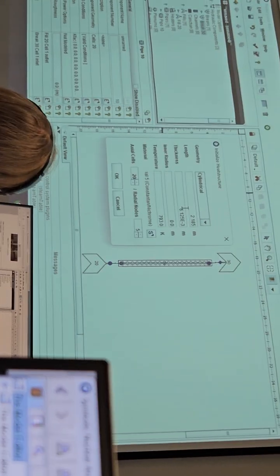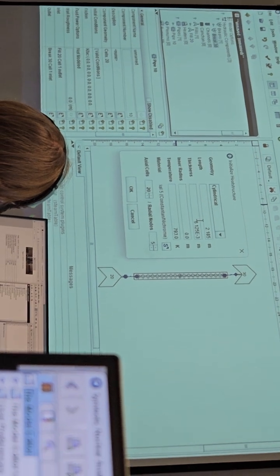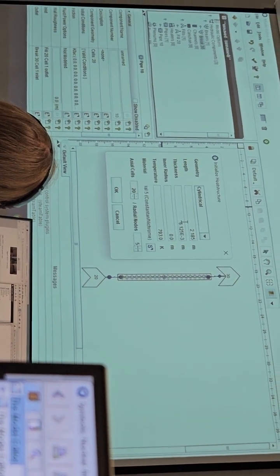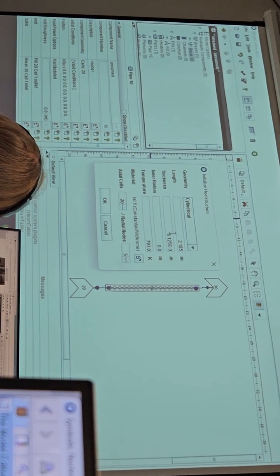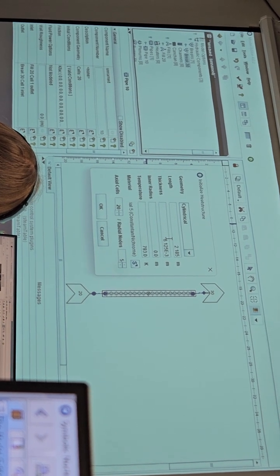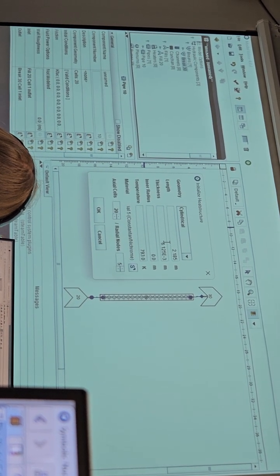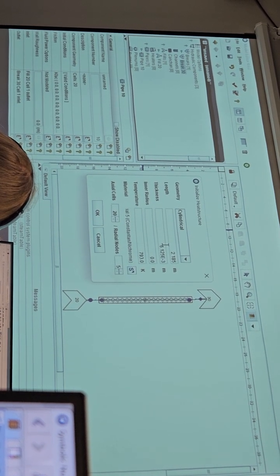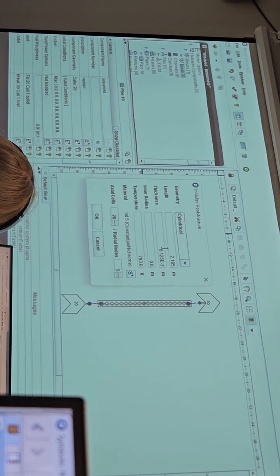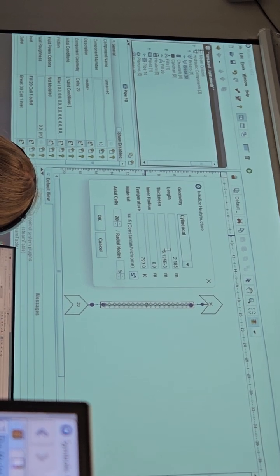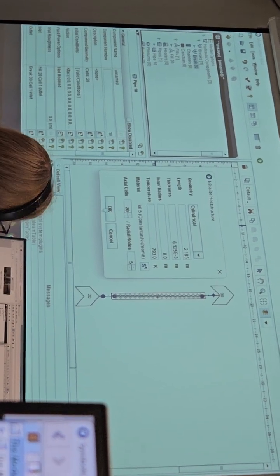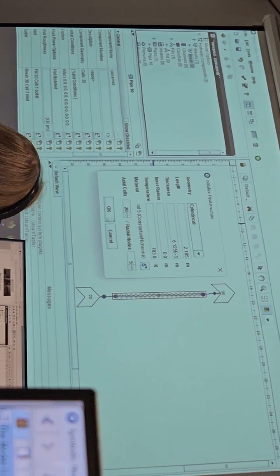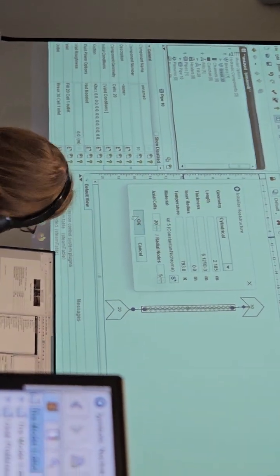So then you will be able to analyze the central rod temperature and the outer surface temperature, and also it is possible to check the temperature layer by layer. It is for separate investigations. For our case, 5 radial nodes is quite enough. So then we just can press OK.